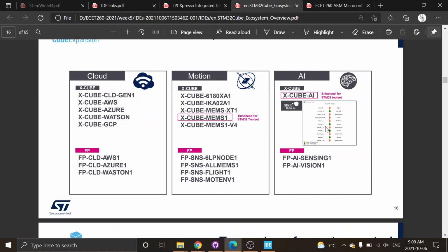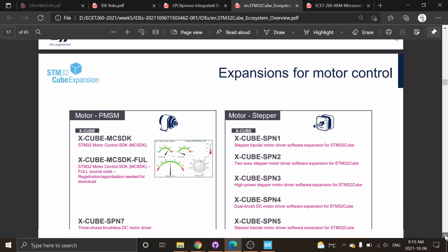It has all the smarts to be able to do that, and it has what's known as an FSMC module to go out to a parallel display. I have a 7-inch display, for instance, on it and all that. It takes a bunch more wiring. We're going to use the SPI interface just because it's a little less wiring. But it has vision abilities and things like that as well.